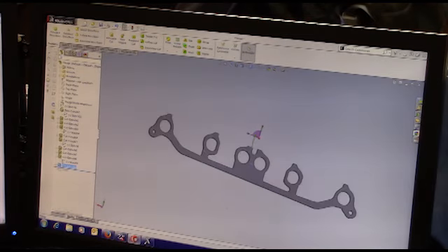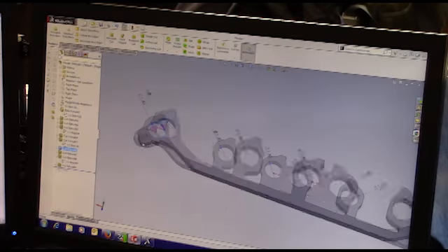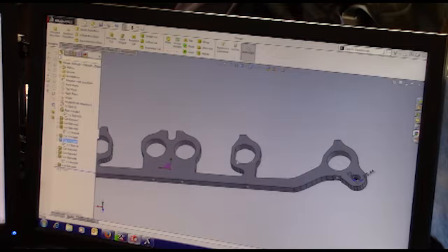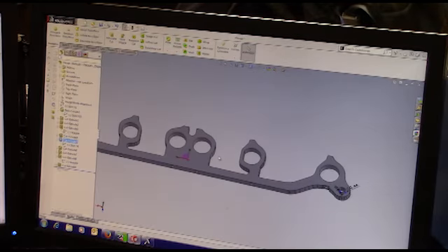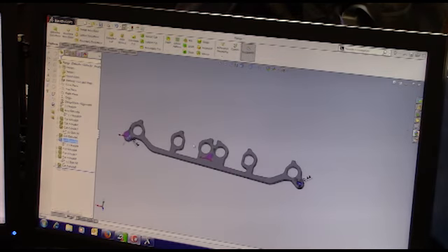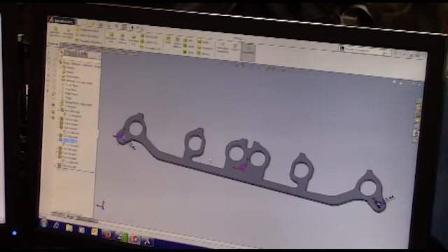So those are some of the design considerations we took into play. We made these holes true. We made all these pinholes true. So now they're real features that are machined, and again, the changes we made are down to the thousandths of an inch, so they don't impact the function. So what we're going to do now is take this model and create some drawings for it, and then we're going to dump it into our CAM package, and I'm going to show you that real quickly.